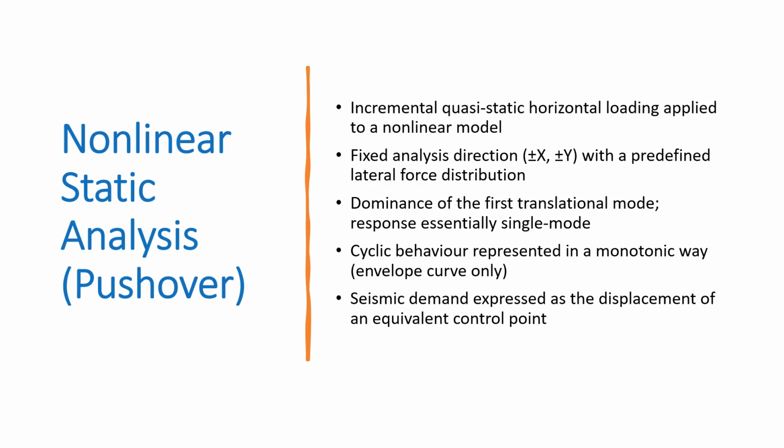In general, pushover analysis holds a significant number of advantages, and it is definitely a preferable method for a system like a URM building, in which the nonlinear response is evident and relevant since the beginning of the deformation.